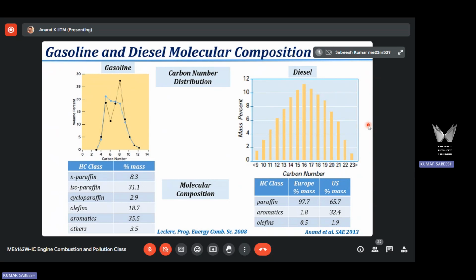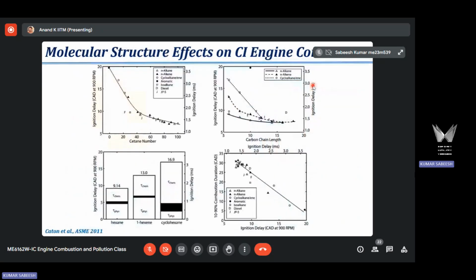So fuel travels a considerable path from the tank to the injector for each cycle. When you have a very low ambient temperature and you have to deal with such heavier fuel, this heavier fuel will start to solidify. It will start to form something called wax crystals in the fuel line. Once the crystals are formed, the fluidity will get reduced. The fuel may not be able to flow quickly from the tank region to the injector. The worst case scenario is if the temperature is too low, the wax crystal formation will increase and the crystals will finally clog the fuel filter. Once the filter is clogged, you know what will happen. There is no more fuel delivery to the injector, no more fuel delivery to the cylinder. The engine will become inoperative. This is the severity of the problem in dealing with such a high molecular weight hydrocarbon based fuel in cold ambient conditions.